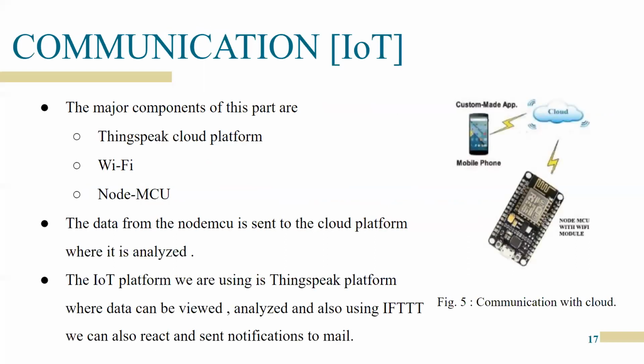Yeah, so coming to the next part, which is the communication part or the IoT part. Actually, this IoT part consists of mainly three things: the ThingSpeak cloud platform, Wi-Fi, and Node MCU. As you can see, the data from the sensor is coming to the Node MCU, and we need to send this data to a cloud platform or store it in a database. For that, we are using the ThingSpeak platform because it is a professional one, and it is also user-friendly, with a wide range of applications.